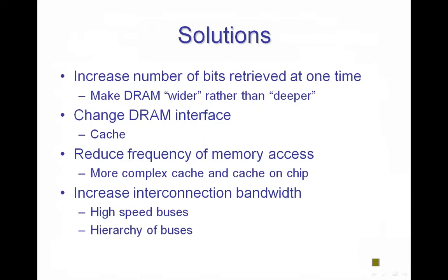Solution: increase the number of bits retrieved at one time, make DRAM wider rather than deeper, change the DRAM interface, use a cache, reduce frequency of memory access, more complex cache and cache on a chip, increase interconnection bandwidth, high speed buses, and hierarchy of buses.